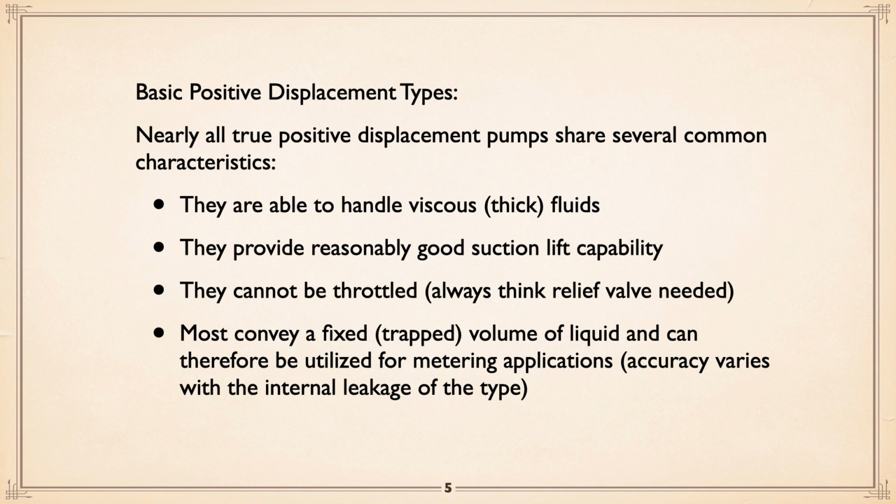Now, positive displacement pumps, and there's a lot of them. They have several things in common. They are able to handle viscous or thick fluids. They provide reasonably good suction lift capability. They cannot be throttled. Keep that in mind.